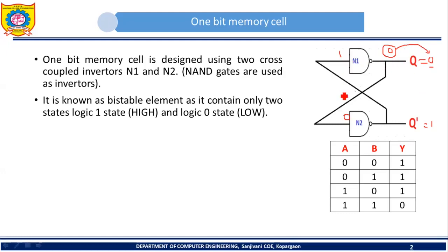So now I can say that this particular circuit is stable. In which state? Low state. It is stable, so this state is not going to change. Please try to understand. In other words, I can say that in this circuit now 0 has been latched. 0 has been stored. It cannot be changed. This circuit now is acting as a memory. Now consider another case.